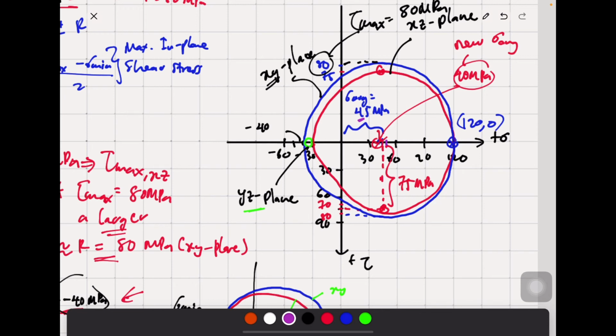From there we need to have 2 points, remember, to draw the Mohr circle, and out of this we have the information given from the question. Sigma x is 90 megapascal, right? 90 megapascal, and the tau maximum for the x-set plane is 60, somewhere around here.